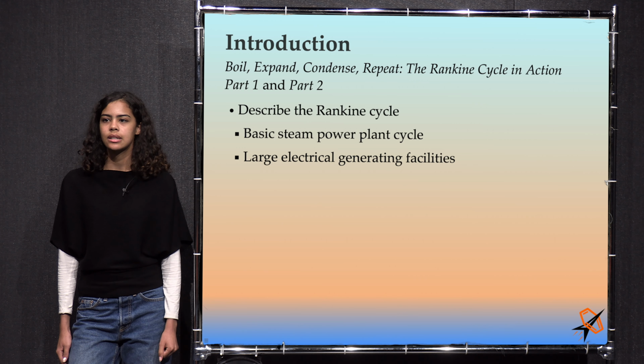At 500 degrees Celsius and 80 bar in the superheated region, we have that H hat is 3399.4 kilojoules per kilogram, and S hat is 6.7264 kilojoules per kilogram Kelvin. We'll start at point A and calculate the work in the pump.